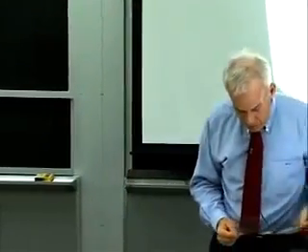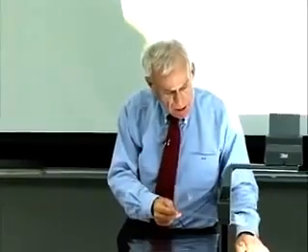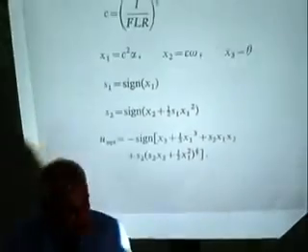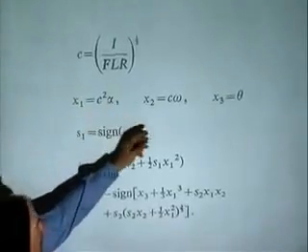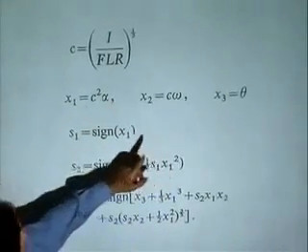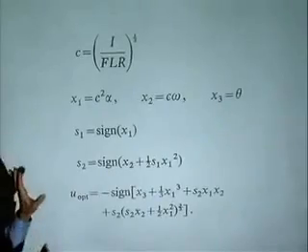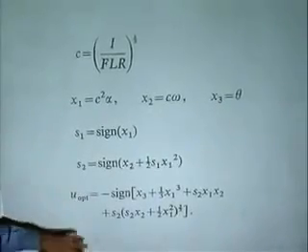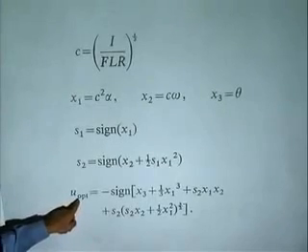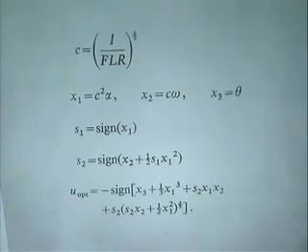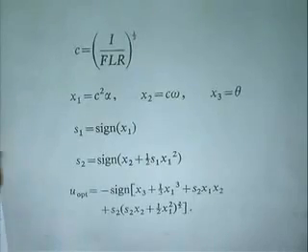So the control law that got programmed was, this is the optimal control law. I don't expect you to understand it, but it's a memoryless function of the 3 state variables, bias, angular acceleration, angular velocity, and attitude error. At each point in time that you know that state, this is a memoryless calculation that tells you what the optimal control, which way to be driving that signal. That had to be programmed up.